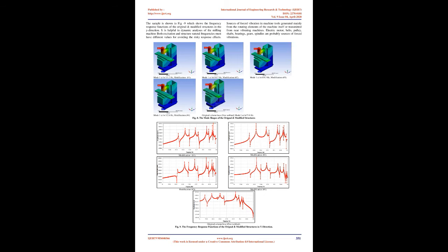The previous equation can be rewritten in the following form by assuming free vibrations and ignoring damping. Also, the following equation can be formulated considering the harmonic motion, i.e., U equals U sin(ωt), as follows, where the angular frequency is equal to the square root of the eigenvalues. Also, the structure's circular natural frequencies f, in cycles per second, can be calculated as follows.